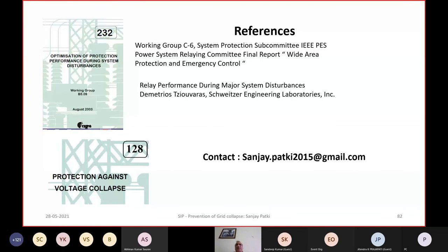Of course, that higher time delay will not be very damaging, because a fault near neutral will definitely have less intensity in terms of fault level. So that higher time delay in that case can be tolerated. But high-speed protection is desirable if the HT side is say 400 kV and so on. Restricted earth fault can be easily added if you have a numerical relay. Differential and restricted earth fault both can be configured in the same relay.